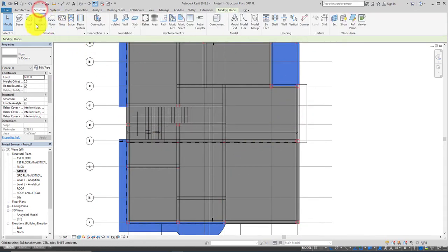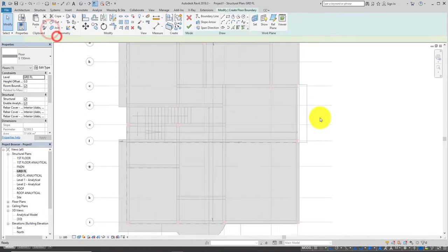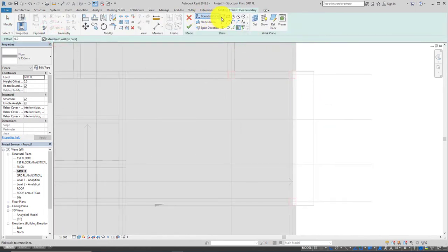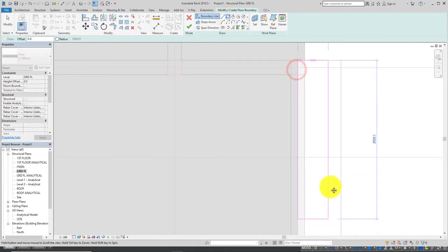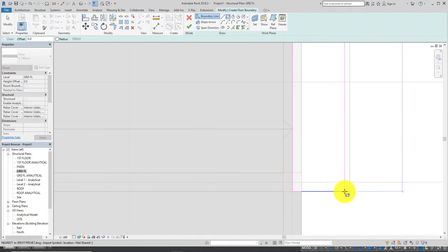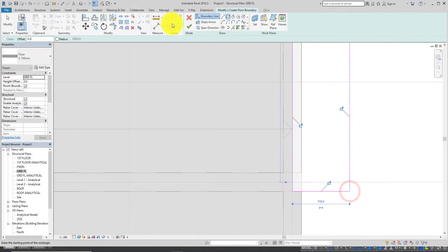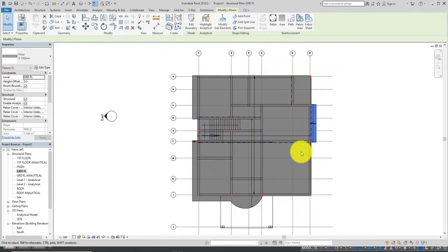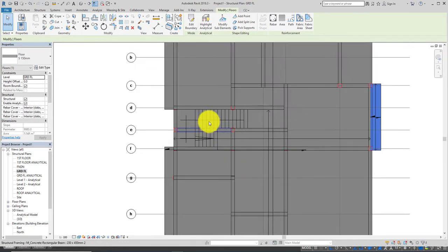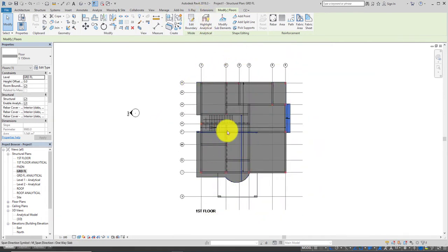So we'll go to structure again, we'll pick on floor, structural floors. So we'll come back and pick our line so that we'll be able to just draw, or let's just pick the rectangle so that we'll have from here down to this point and just say finish. So that is how to represent your floor. And then you want to represent your stairs, you are going to have an opening here, and definitely that's going to be provided before you click on your finish button.